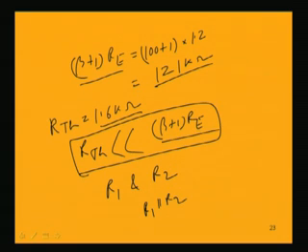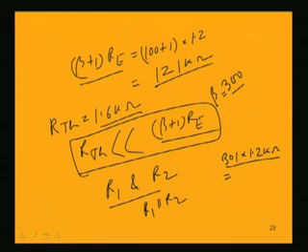In the other case, for this example, if we even consider the change of beta, the new value of beta is 300, and for that case the condition will still be maintained. That can be checked: if beta is equal to 300, beta plus 1 is 301, and 301 into 1.2 k will still be higher as compared to this Thevenin resistance of 1.6 kilo ohm.